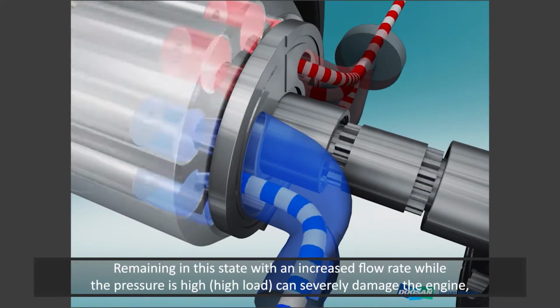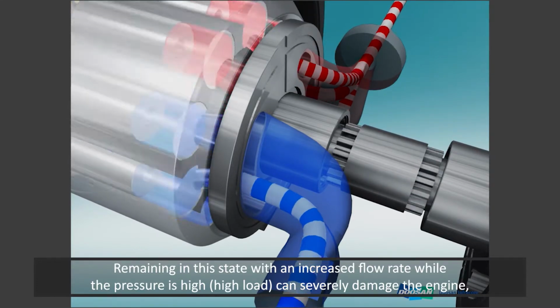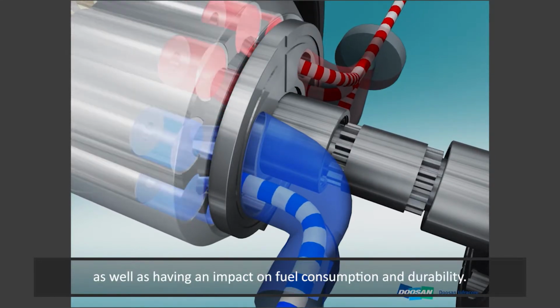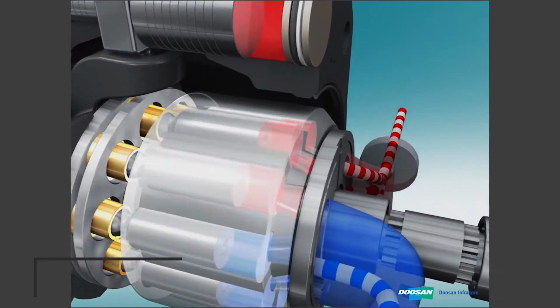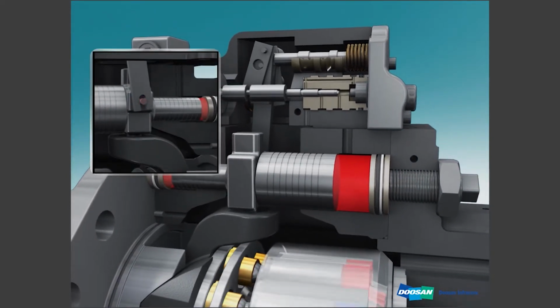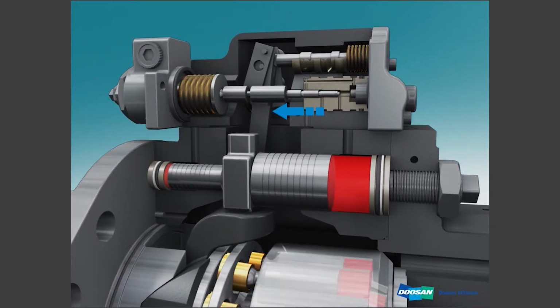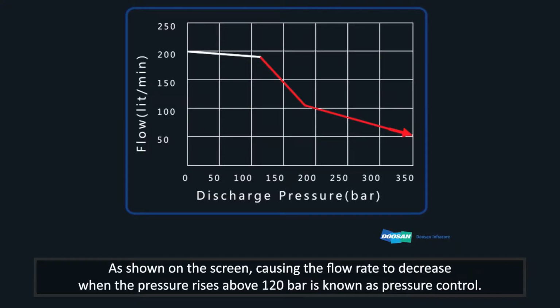Remaining in this state with an increased flow rate while the pressure is high load can severely damage the engine, as well as having an impact on fuel consumption and durability. As shown on the screen, causing the flow rate to decrease when the pressure rises above 120 bar is known as pressure control.